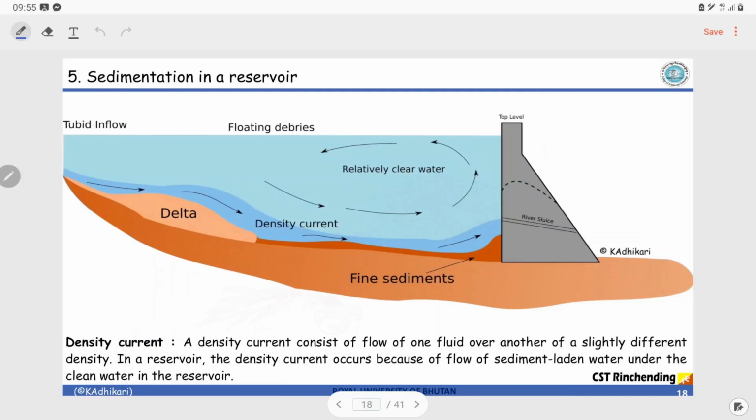This diagram shows the profile of a dam. Start from the point where the ponding has started. What you will see is that eventually the water is very turbid, and the material that the river was carrying will start to deposit because it has no energy to carry it further down. So it will form a deltaic region upstream of a dam.